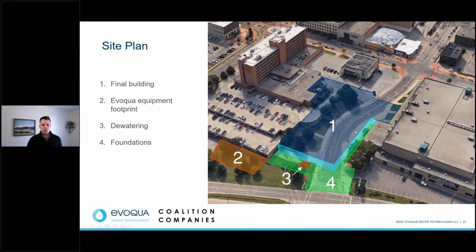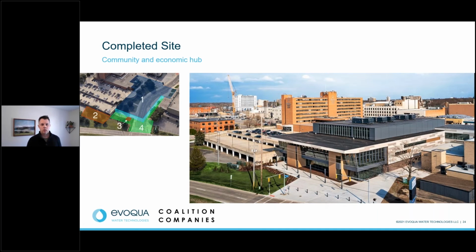Our schedule, because of the delay, only extended 30 days. We were able to recapture that throughout the course of construction by resequencing the rest of the project. So it ended up with a net zero delay for the entire project. And then the design had really minimal changes. We figured out a couple different ways to have spread footings, a different type of footing that helped us from not having to dig quite as far. So it really ended up being really zero cost to the project outside of the dewatering, treatment, and everything else that we had going on.